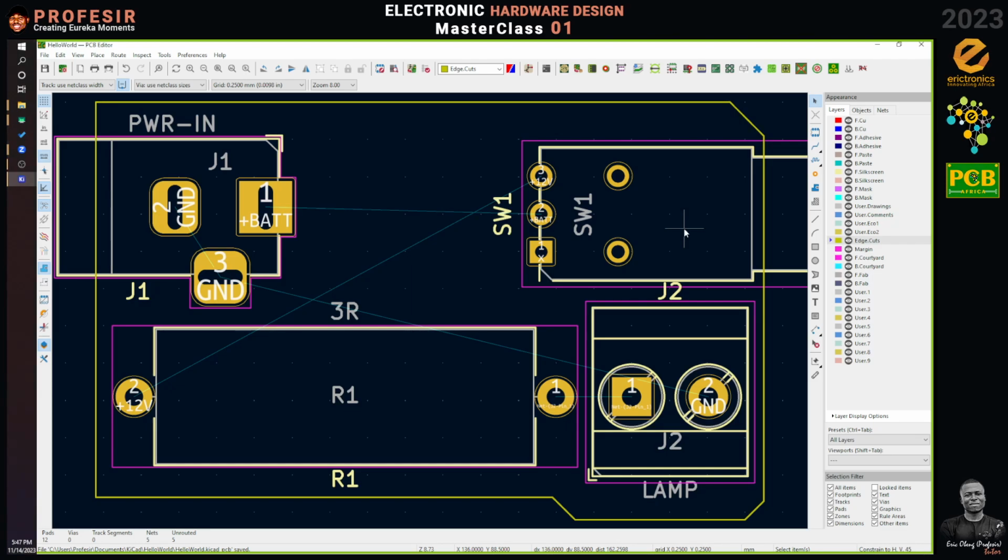Are you going to etch this board locally, or are you going to etch it professionally? Because if you are going to etch it professionally, then you have the flexibility of doing certain things, right? If you are going to do it locally, then you can't do certain things. Okay, great. Now, let's assume we are going to etch this board locally. We are not going to send it to China. We are going to etch it locally.